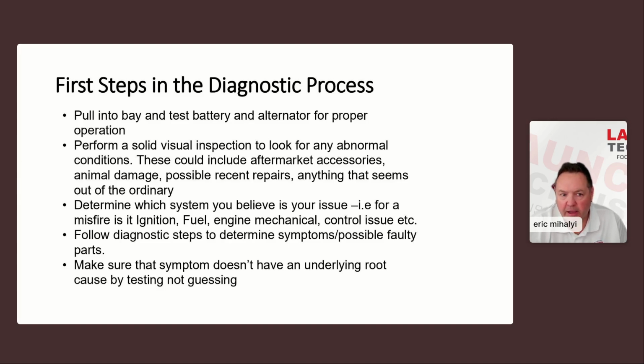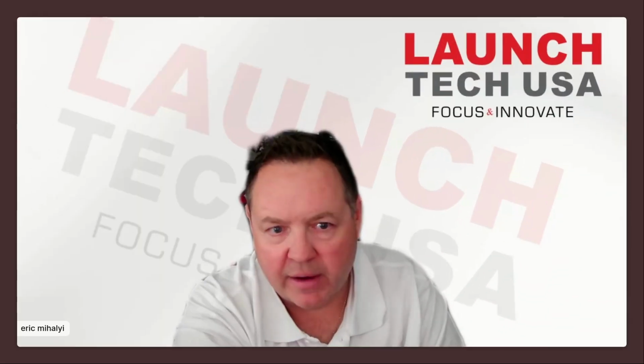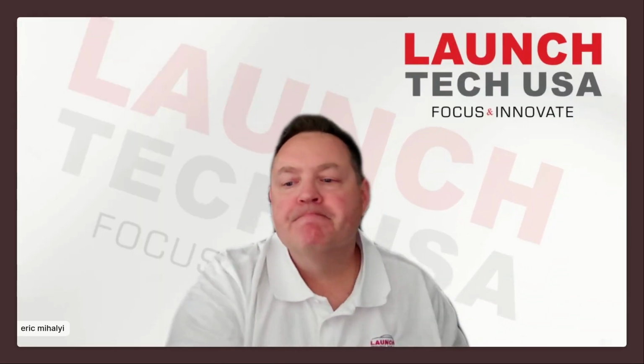You're going to fix the car probably and send it down the road, and the customer is like, oh yeah, the light went out and I don't have that misfire anymore. Well, what's going to happen is 4 months later, the car's going to come back and coil number 4 is going to be burned out again. And you're going to start blaming the parts guy: oh, this XYZ brand coil is the problem. No, you fixed the symptom, not the root cause. So think about it when you're replacing a part, especially something like a coil where one went bad. Why did that one go bad? Why did just one go bad? There's likely an underlying cause.